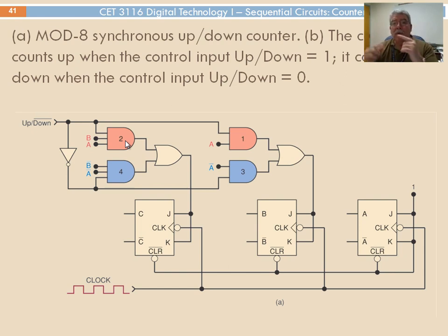So in this case, we use an AND gate, and then we bring the inputs from A and B, and when both are 1, then the AND gate will be 1, and that will go feeding back into the first flip-flop, and they will make a toggle, right? Well, not to the first flip-flop, to the third flip-flop, okay? We'll make a toggle. All right.